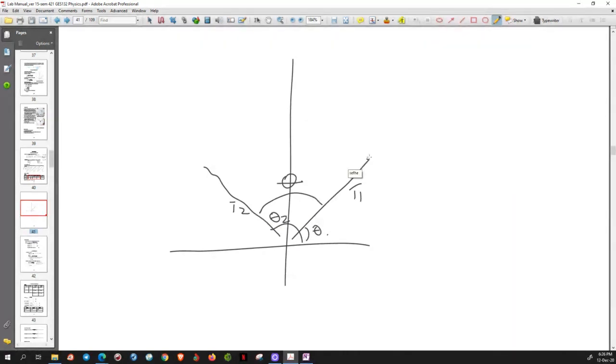Next, you will measure theta from here. So you will continue this with a small line, and then measure theta. This angle should go there, okay? And from that angle, you will make or transfer your T2. It becomes T2 prime. The angle theta prime and theta should be the same.